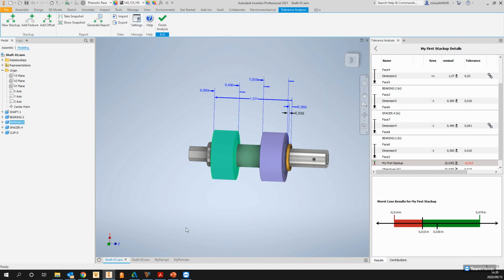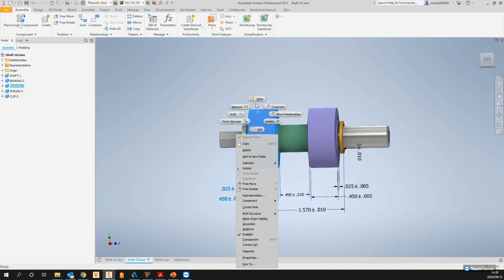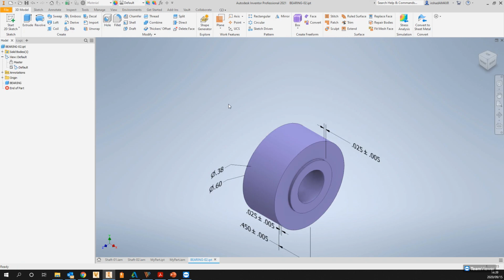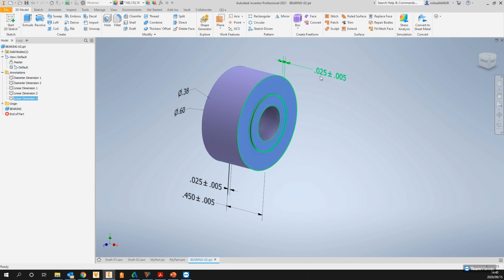For example, here, let's go here. You'd have to open each one of your parts, right? You'd have to go and click on your dimension and go to show dimensions, or you have to go to dimension editor and base, or you can go from your parameters and edit all of these things here. I'm not sure where these are located, but basically you would need to go in and change to specify that you want a tolerance on these. However,